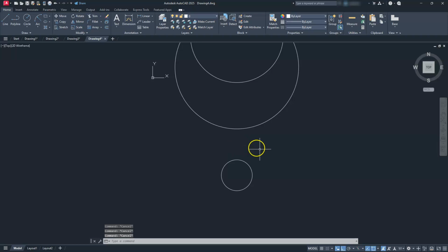Okay, so in the intro, I told you that the distance going across is 10, right? We can automatically see that this circle has a radius of 5. We don't really have to figure out that number. We can draw lines just from this quadrant going straight up. And I'll do the exact same thing here on the other side. And that's going to give us that distance, right? So we don't have to figure it out or do anything of that nature. The geometry is going to do that for us. Let's go ahead and trim off this portion here.